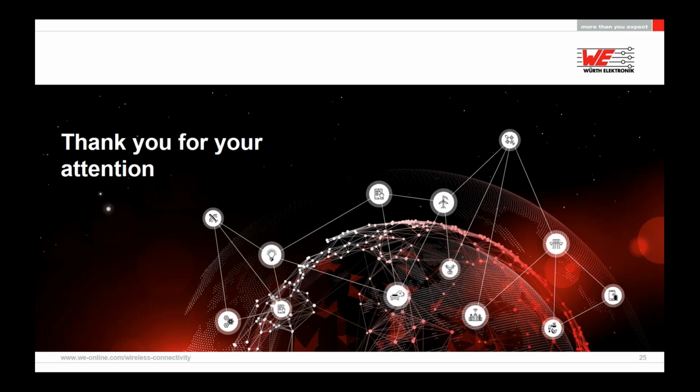Okay, Matthias, thank you very much. One question, which I had a little bit earlier on, is hardware related. When would you use an external antenna and when do you prefer an internal antenna? Well, there's a lot of antenna theory. I know that in essence, if you want good range, a long range, you'd use an external antenna. For shorter distance within a building, you'd probably use an internal PCB or chip antenna.